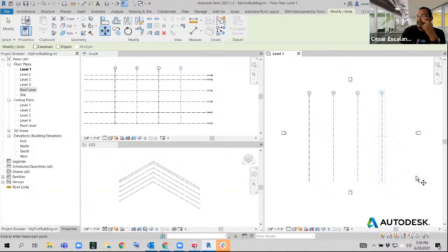When you move an object, Revit presents you also with these options. You can move elements in a constrained mode, or you can create multiple moves. If you enable constraint, this is the equivalent of F8 in AutoCAD. You just move an element in an orthogonal direction, either 90 degrees or 0 degrees.